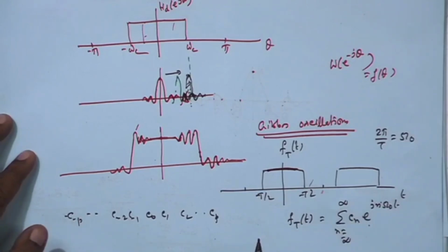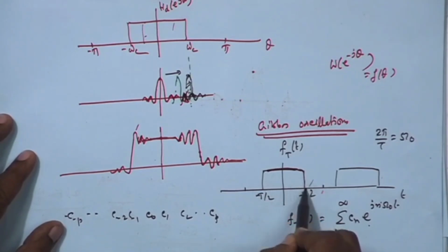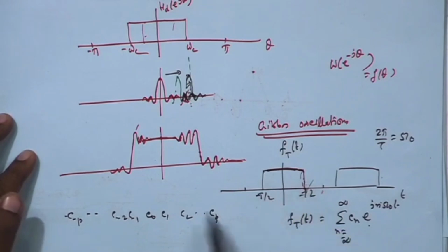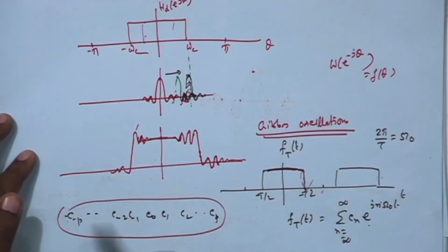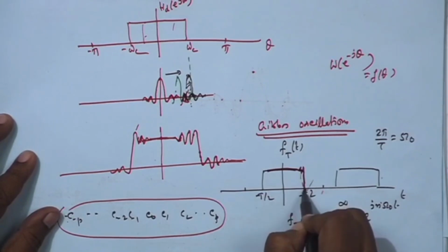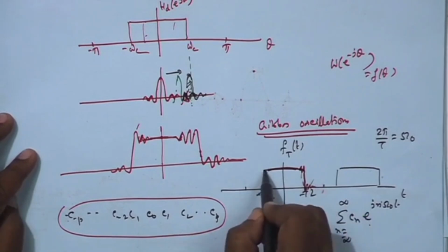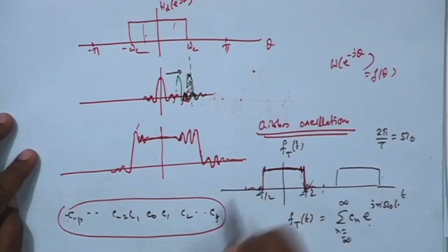So, the low frequency part, whereas the high frequency part is present here, where there is an abrupt change from high to low immediately. So, high frequency components are locally here. This part will be largely mismatched by a summation taking only from minus p to p, because those high frequency components will not be there. Therefore, here we will have deviation from this. In fact, we see oscillations. If we do not take those additional components, there will be oscillations. This is called Gibbs oscillations.